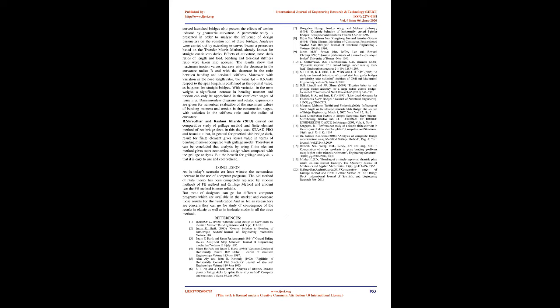Analyses were carried out by extending to curved beams a procedure based on the transfer matrix method, already known for straight continuous decks. Effects of curvature, nose-deck ratios of length and load, and bending and torsional stiffness ratio were taken into account. The results show that maximum torsion values increase with the decrease in the curvature radius r and with the decrease in the ratio between bending and torsional stiffness. Moreover, with variation in the nose length ratio, the value ln/L equal to 0.60 with respect to the span length is confirmed as the optimal value, as happens for straight bridges.